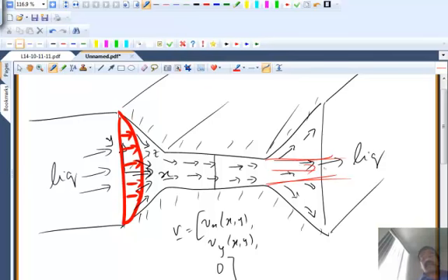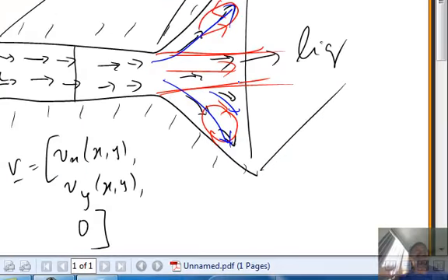Okay, and I might in fact see a kind of recirculation, meaning there is a kind of a wake that forms here at high Reynolds number. But at low Reynolds number, I will have the thing expanding and going like this. Okay, that's what my intuition tells me, and I can build an experiment to see whether it is true, or I can go to Comsol and solve it these days. So easy to solve. Okay, so we are going to see whether.